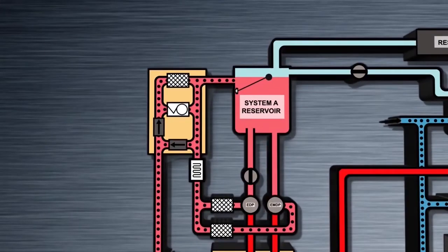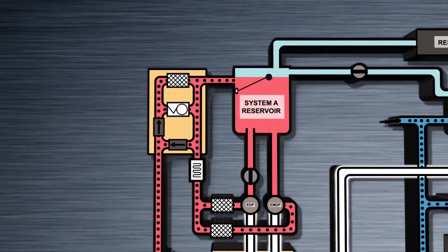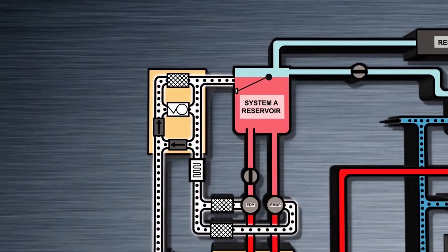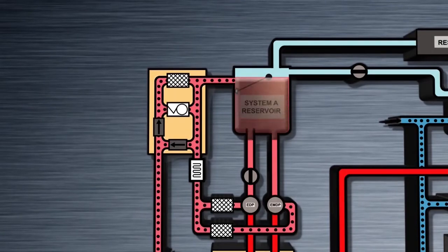Each pump has 2 outputs, an output pressure line and a case drain line. The output pressure line does as the name suggests. It pressurizes and provides fluid to the rest of the hydraulic system. The case drain line drains a smaller quantity of hydraulic fluid away to be filtered and cooled. It is this case drain fluid that passes through the heat exchangers in the 2 main fuel tanks.